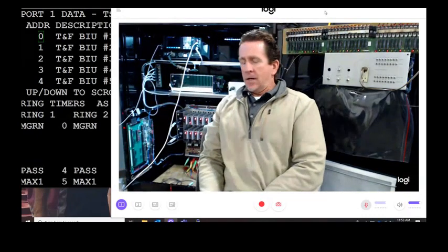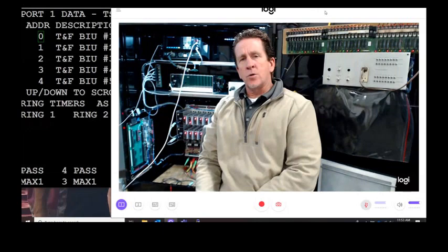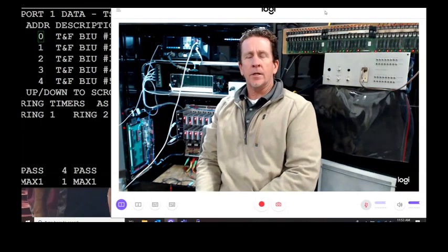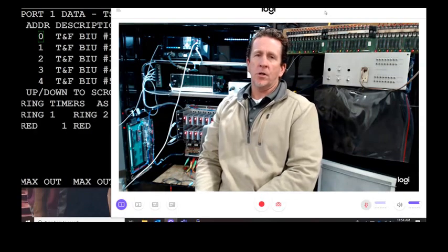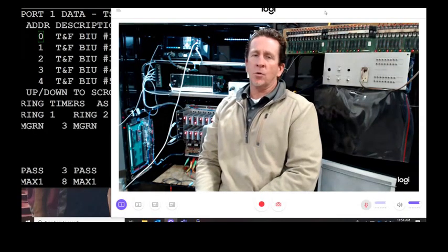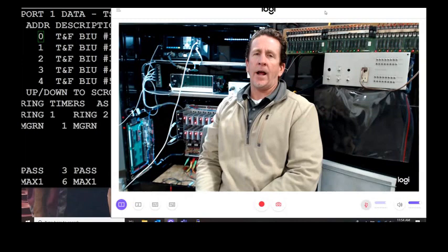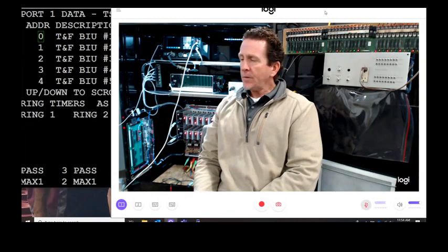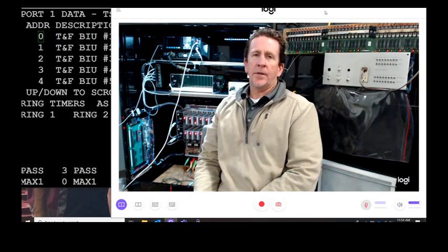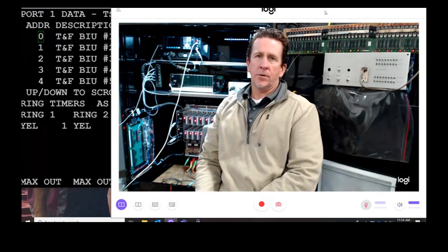Again, anything that you get coming from Ocean State should all be programmed properly. Anything that you do in the field, once you default the controller, it defaults to a TS1, so all that TS2 stuff is turned off and it has to be turned on in that 4/7 screen. The 3 BIUs and the MMU and the controller BIU.